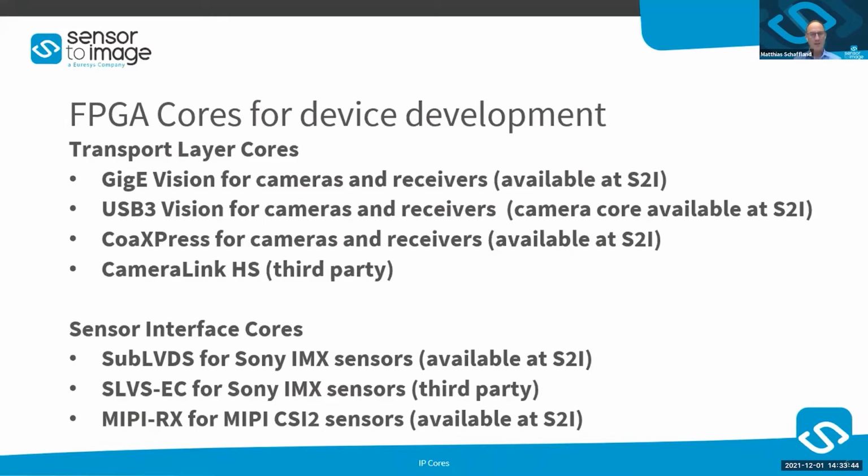For other sensors, especially the Sony IMX sensor series, they come with different interfaces. An older one is the sub-LVDS interface. Here we offer an IP core, so you can easily integrate that. For other ones like SLVS-EC, there are IP cores available from third parties.